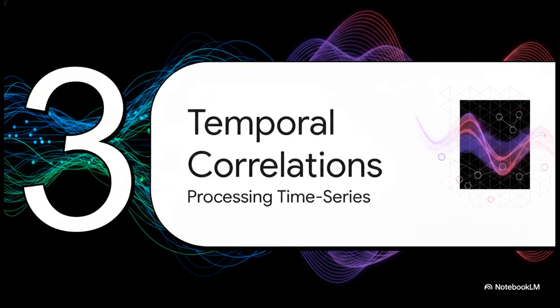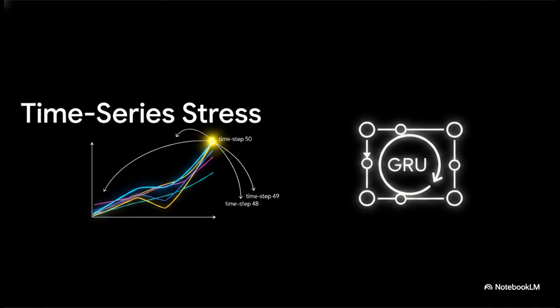All right, Section 3, temporal correlations in data, processing time series stress. So the big takeaway here is that stress responses in these inelastic materials are not just isolated static data points. You have to treat them as multivariate time series data. And the reason comes down to physics. Because of that path-dependent plasticity we talked about, the stress state of the material at, say, time step 50 is directly linked to what happened to it at time steps 48 and 49. In fact, the researchers proved through autocorrelation analysis that these temporal correlations stretch up to 10 time increments into the past. So whatever neural network you choose for this task, it absolutely has to have a memory.